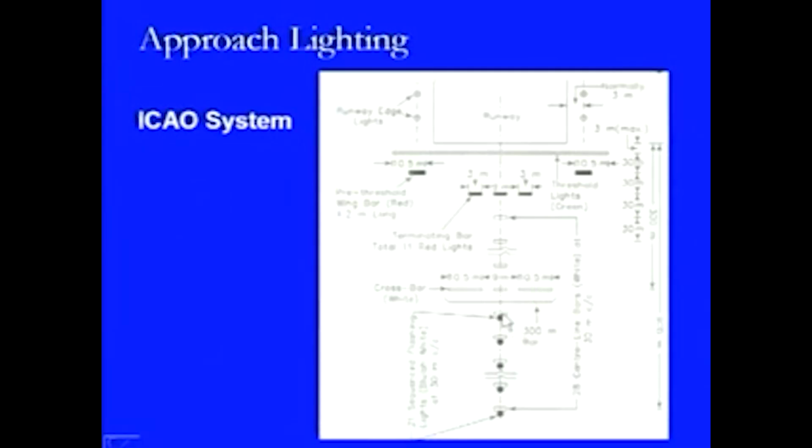Here, for some distance, we are providing these bars along with the flashing lights, and these are again the 21 flashing lights which are placed at 30 meter center to center distance with each other, and they are bluish white in color. So, that is the combination which is provided, and in this case also it is provided for a distance of 900 meters with respect to the end of the runway strip.